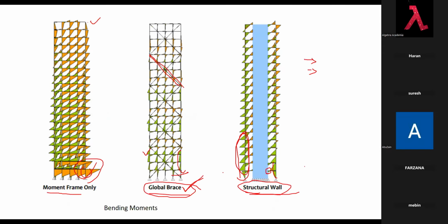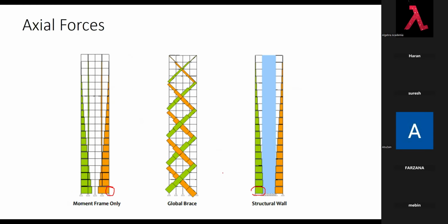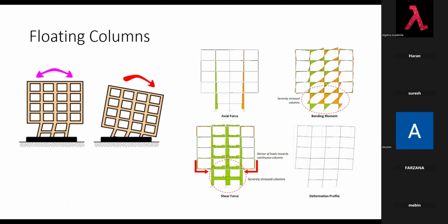So this is very important to understand. So bracing and shear force. I'll just go to another concept, floating columns. What happened? We just model this floating column. Floating column means the column is coming from the top story, but suddenly there is no column here. It is like an overhang. If it is an overhang, the demand in the ground story column is going to be much higher. Suddenly it is going to be higher, and my shear force is also going to be higher.